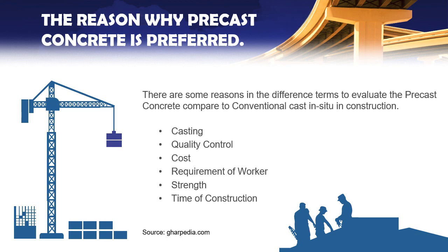Next, for the strength, high-strength concrete can be used for precast concrete because it is in controlled conditions, and for cast in situ, it will be difficult to use high-strength concrete as it depends on the site conditions and resources available. Lastly, precast concrete uses less time compared to cast in situ.